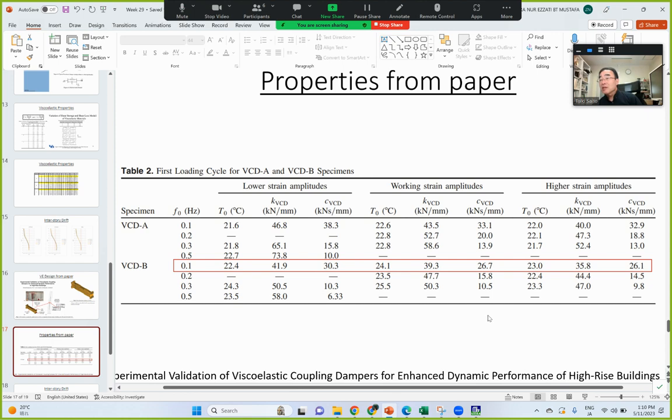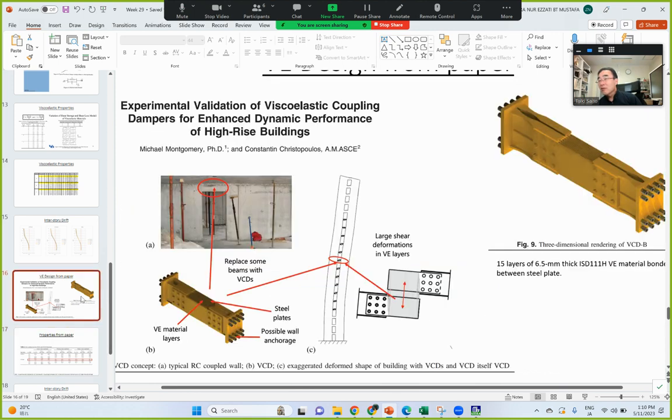And what is the damper you tried? Slide 14, sensei. It has an elastic damper, and at the end it has a stiffener. I think this is a good idea because this damper is very strong. In your case, it is exceeding almost 600 kilonewton.